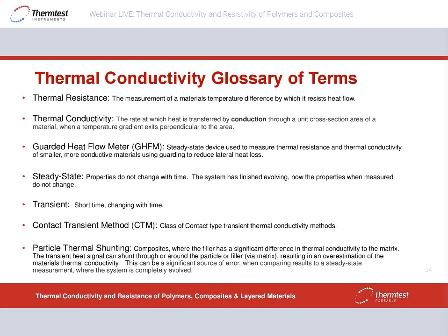So for a layered material, yes. For a layered material, for whatever that might be, anything between the plates, you're measuring through it. So you have that orientation. If you want to switch the orientation and you can prepare a sample 90 degrees to that, you could have the other direction. So that does require preparation of two samples, but if you look at what we've been talking about for true results, that probably is the best way to describe, or rather to measure, these complicated materials.